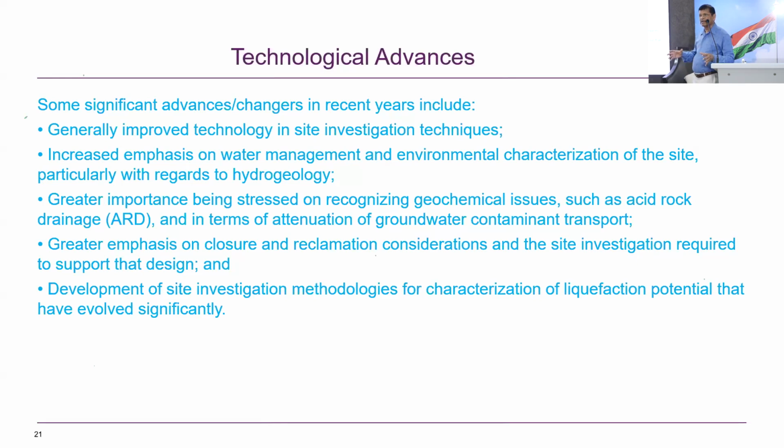What we normally do in the new facility, which will be covered in our next slides in detail, is put in a storm water bypass. We do not allow any storm water into the tailings. It is all diverted outside. Then we also have to look into acid drainage, because most of the copper tailings generate acid even with precipitation. What is coming out is all acid drainage.